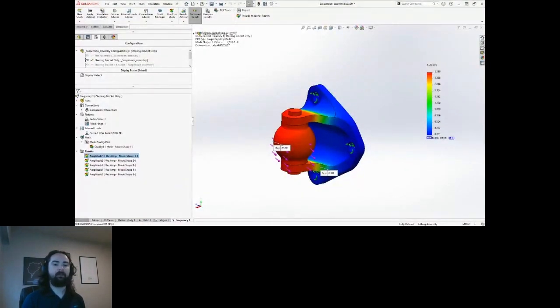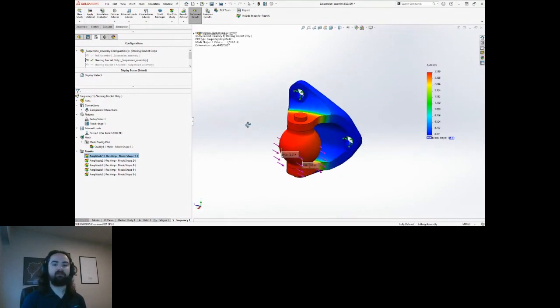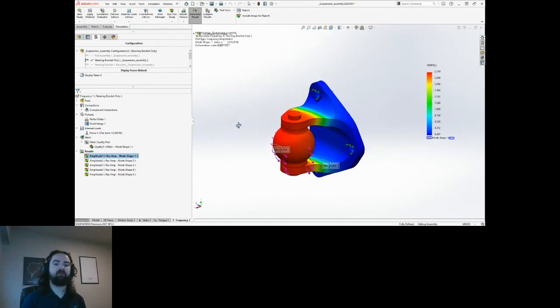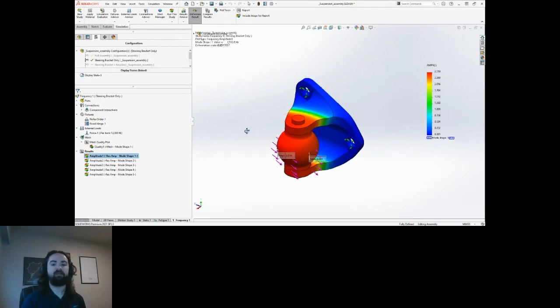All right, so as seen in the clip, Gutierrez's suspension vibrates wildly when he goes over the curbs, which we definitely want to avoid in our design. So let's go ahead and see how ours will do now that the frequency study is done. Now, the frequency range we want to avoid is between 1 and 60 hertz, which is the range of vibrations caused by the car running over curbs like we saw in the video.